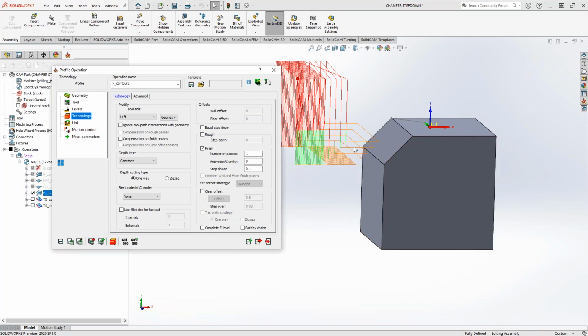Okay. In that case, then this is another opportunity for Contour 3D. If you actually drew in all those lines, and then you can just select them in the order you'd like this thing to go, then you can actually get that profile. Or you chose a series of profiles and you just set your levels to 0, then that can follow that as well.